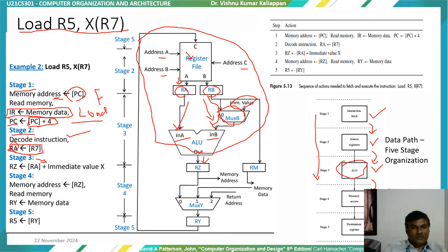So it is written to RZ, after adding the immediate value X. You have that immediate value in X, I am adding it, and then I will get the answer. The fourth stage will be, so RZ. Based on the instruction we have given in our program, either we can push this particular result to the memory address, or we can send it back to the register file.